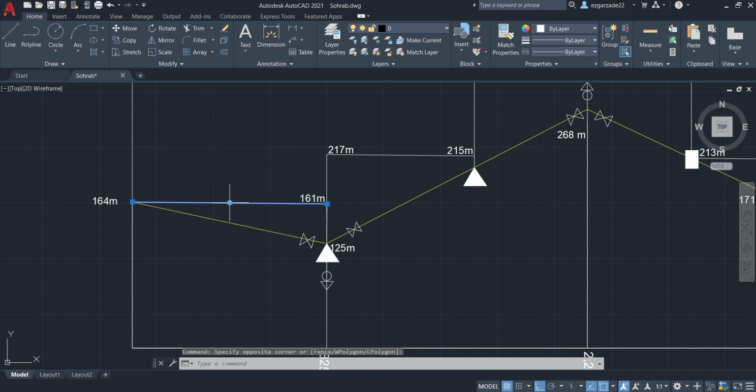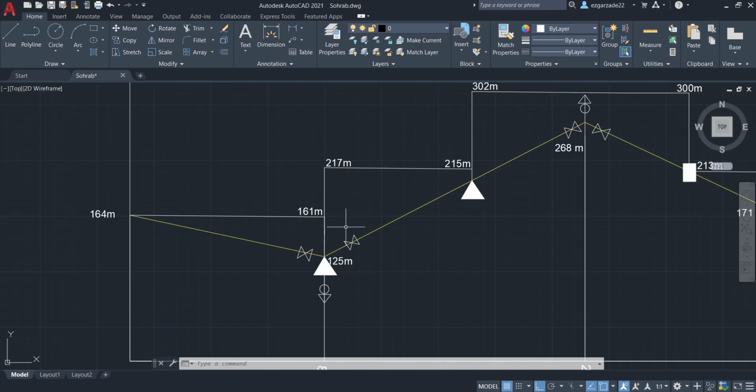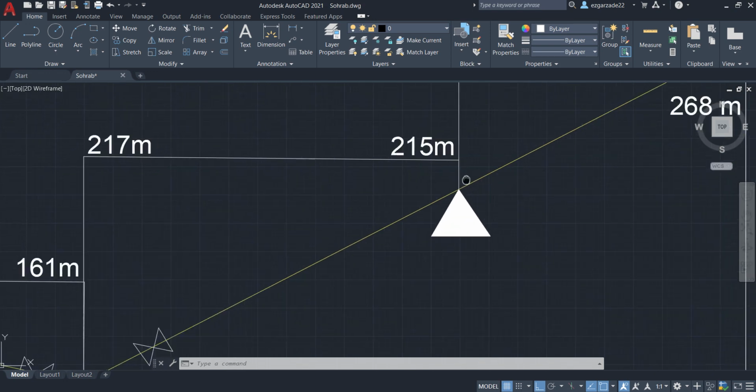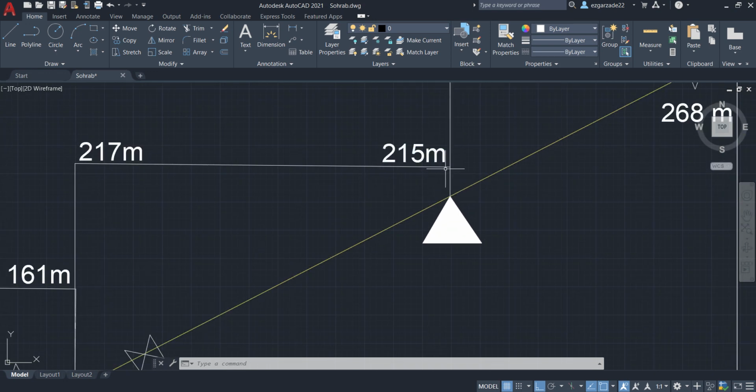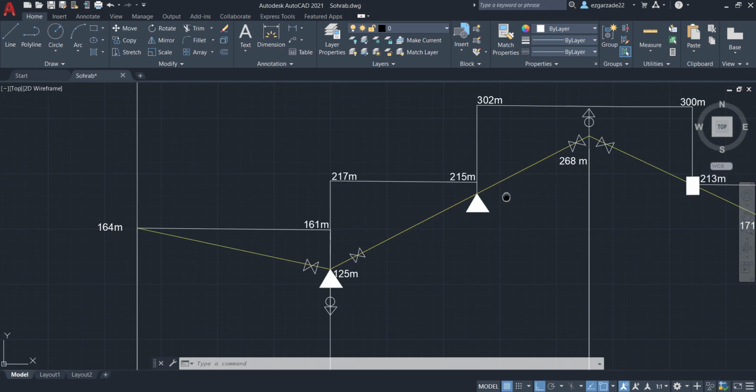So this is my piezometric line, which shows the pressure in the pipe by height, and our maximum allowed pressure in the pipe was 100 meters, so I cannot pass it, and our minimum pressure height is 4 meters, so I cannot go lower than 4 meters at the difference between the piezo line and the transmission line.